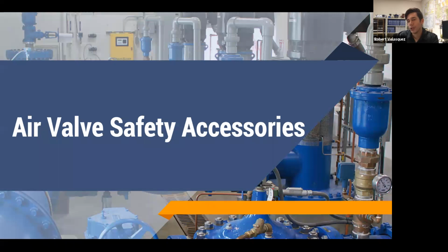Now, when we put air vacuum valves in subterranean vaults, we run into some issues. We run into a cross-contamination risk. So if you have an air vacuum valve that's made to let air in and out of a water system and your vaults flood, because how many of you guys have vaults that flood? You know, it's really common. They're underground. They're basically a giant fishbowl. They fill up with water.